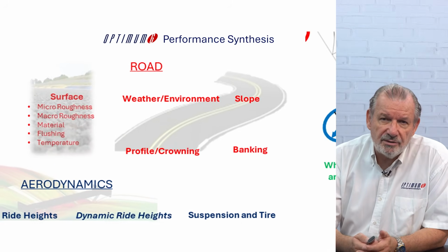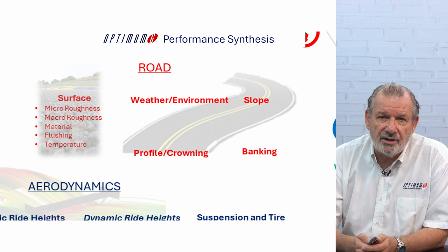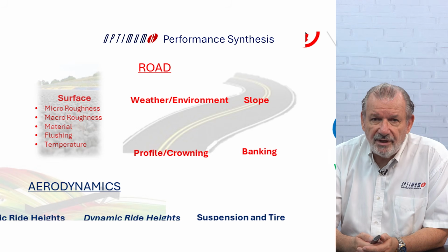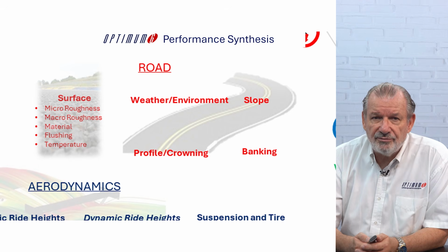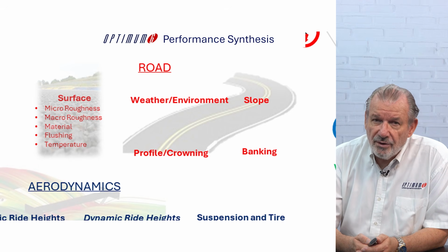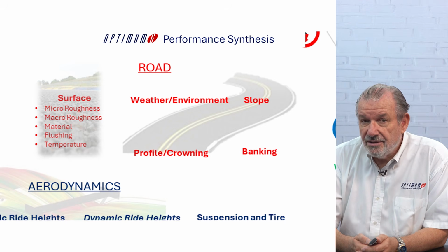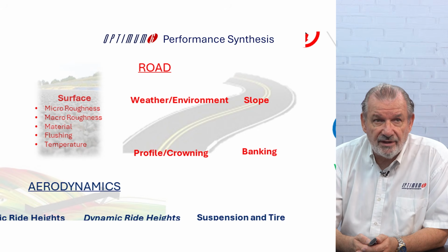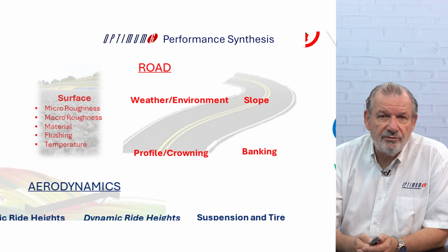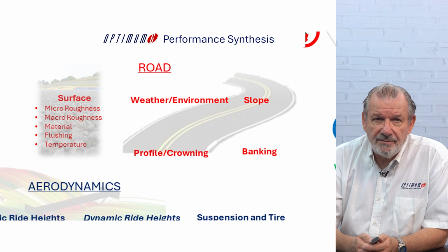We are going back a little bit to the tire here because we need to understand the ground. Understanding the ground is 50% of the problem of the grip. Micro and macro roughness. What's the material? I mean, is it concrete? Is it asphalt? Are you able to evacuate the water easily? It's a big issue in Formula One these days, racing in the rain.